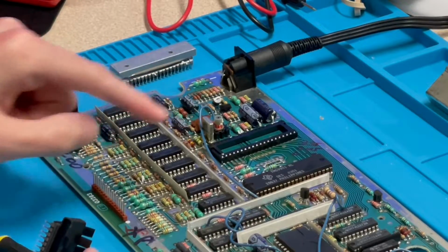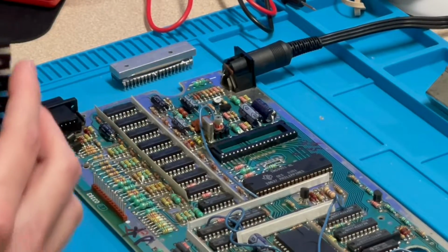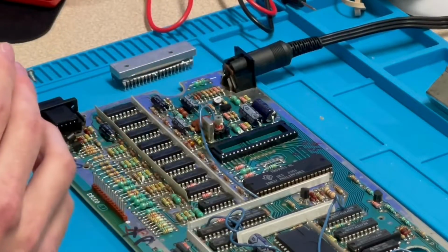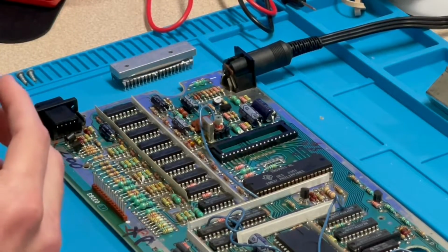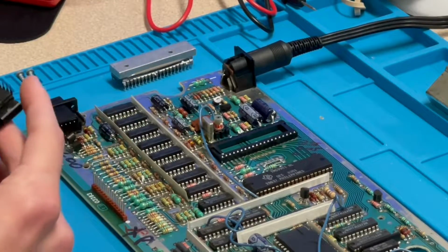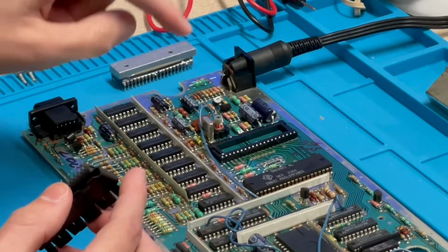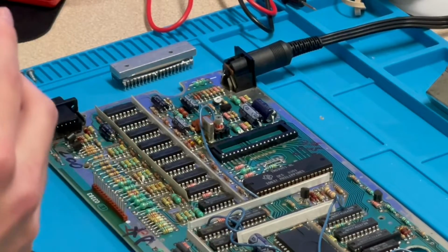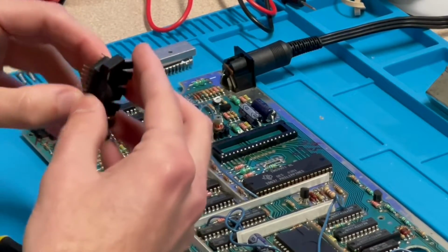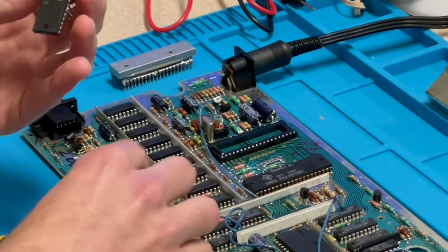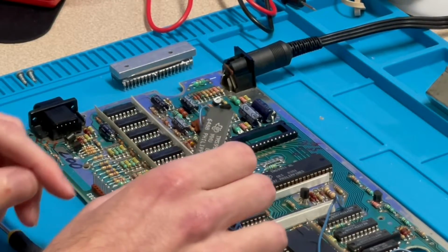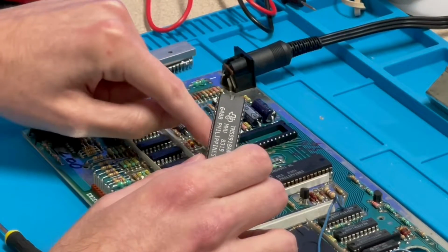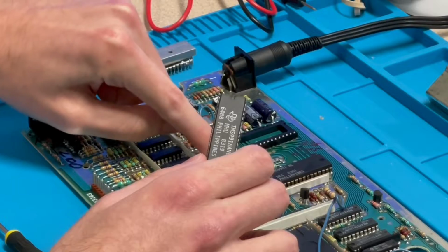So there's the video chip socket, and I have to make sure that when I stick this other video chip in, I stick it in the correct direction. Otherwise, I could kill the chip, because it does matter which way it goes in. And it is actually the reverse orientation on this motherboard, so I have to make sure. This one actually has a heatsink that just slides off. There's no thermal compound. So on the other TI, pin 1 was up here on the top of this socket. On this one, it's down at the bottom. It's marked with a little white arrow.